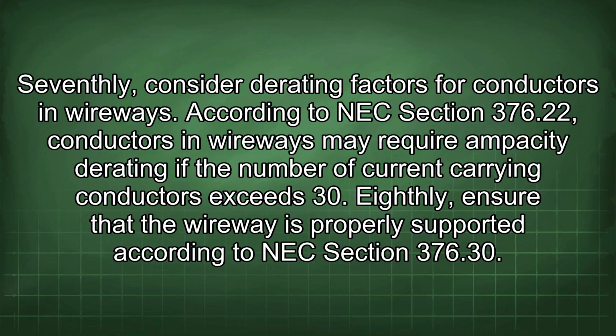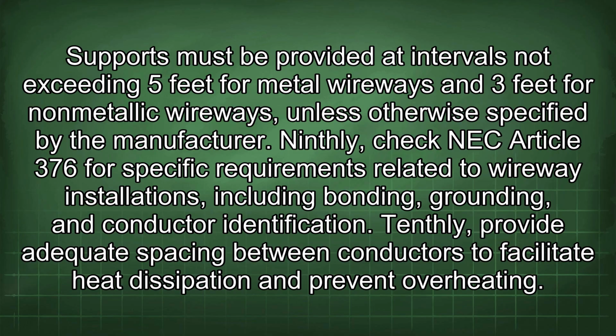Eighthly, ensure that the wireway is properly supported according to NEC section 376.30. Supports must be provided at intervals not exceeding 5 feet for metal wireways and 3 feet for non-metallic wireways, unless otherwise specified by the manufacturer.